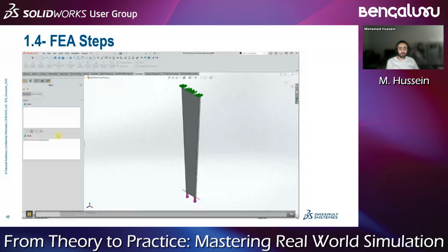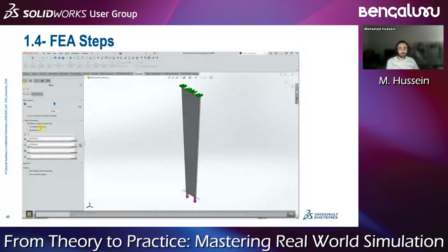For your information, we never finalize a model with a draft quality. Sometimes I start with a draft quality mesh, only for very critical cases or very big examples. I'm only testing what is happening with the draft quality mesh, then I turn it into a high quality mesh. You will see that we have three types of meshes: standard mesh, curvature based mesh, and blended curvature based mesh.